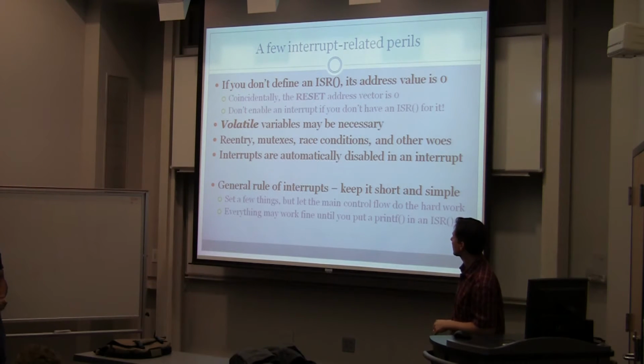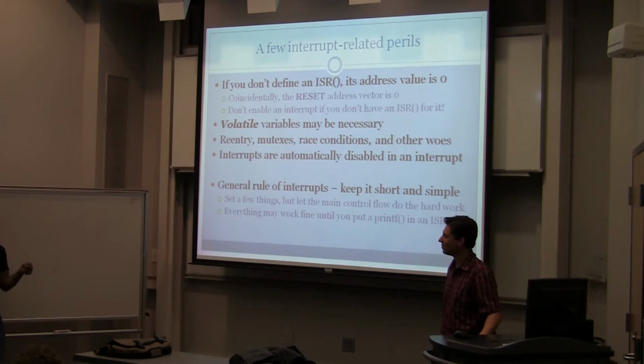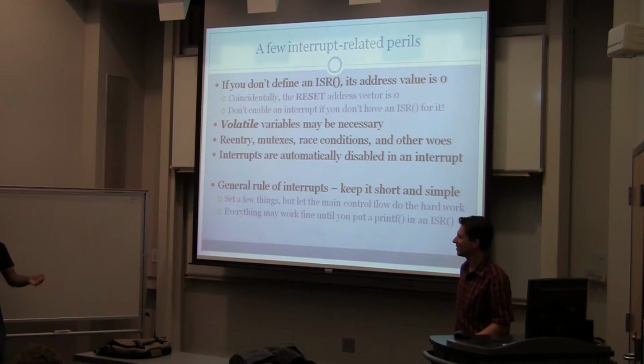Yeah. So basically, all of these boil down to an interrupt can happen at any time, basically immediately. So it's like, oh, you're in the middle of setting this variable, well, I'm going to go and do this other bit of code, right? And that can cause a lot of problems if you're not thinking a little bit about how your code works in your main function or wherever. And when you use multiple interrupts, then you